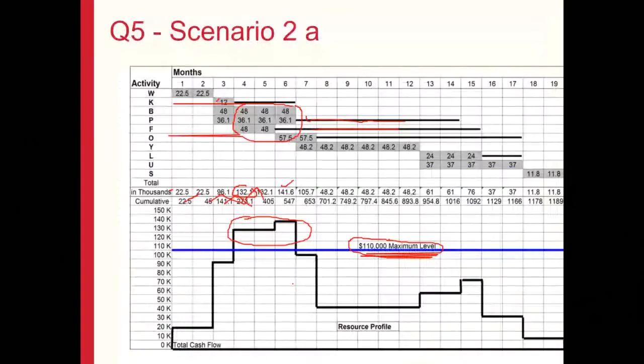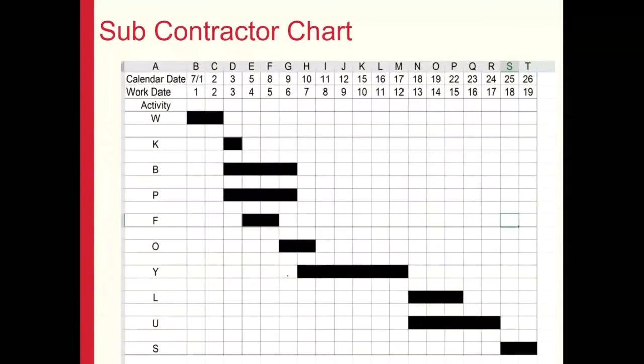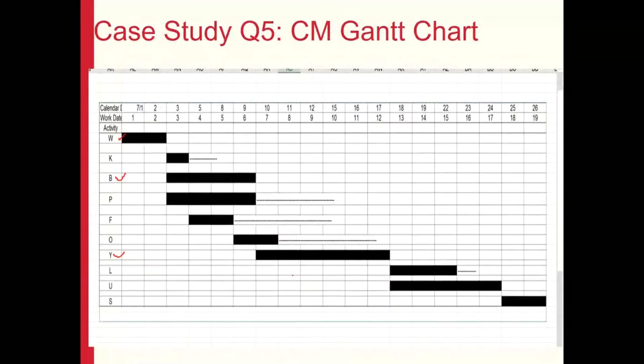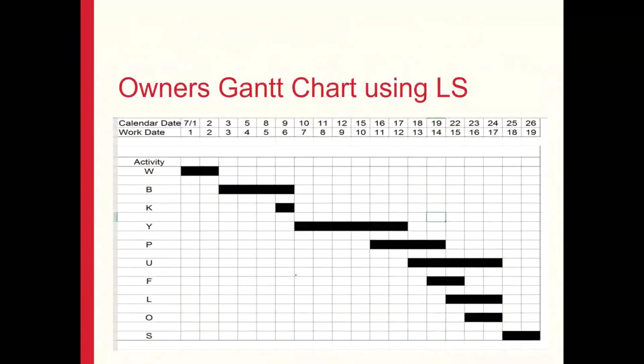So in this problem, we learned how we could use the Gantt chart as an effective communication tool and exchange information which is appropriate, so not sharing too much information or too little information. Now it is unfortunate to say, but very often projects are not delivered in the best team-centric manner. So perhaps there is no point for construction managers sharing all the information about the float with the subcontractors because of this conflict of interest.